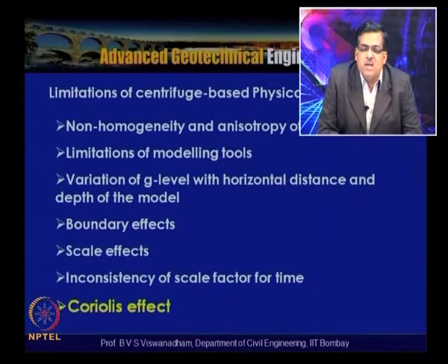Then another thing is that these models are subject to scale effects. One of the predominant effects, which we have discussed, is that because of our inability to model the grain size distribution, the scale effects are evident. These scale effects can be minimized, and we also need to find out how they are affecting the model behavior.